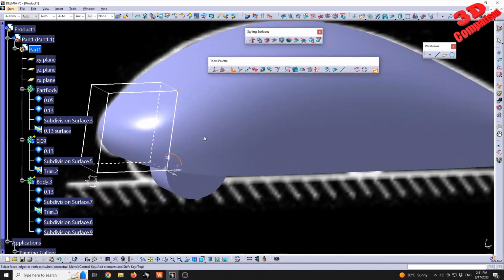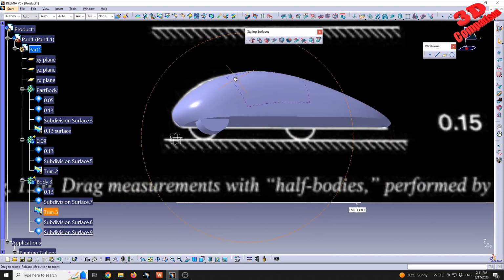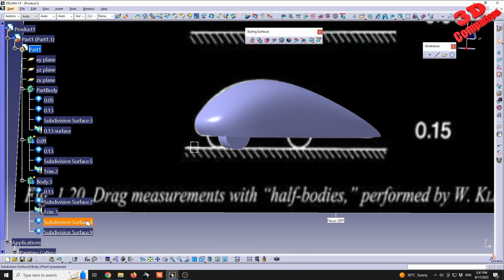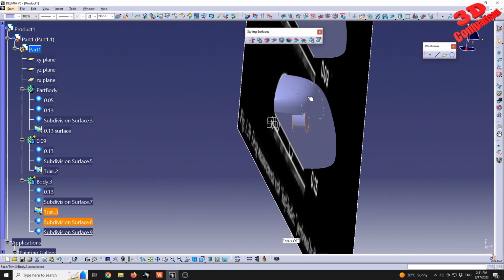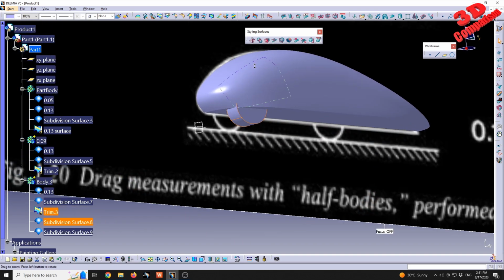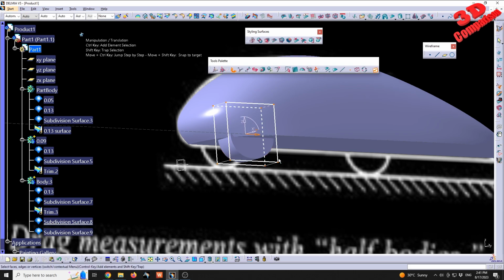We see a little bit of overlap over here between that shape and the wheel, but we can slightly adjust that by either moving the wheel a little bit on the inside or adjusting the width, because now the width is quite large on like that. So let's scale it a little bit and center it. We can also do this in, let's say, post-editing directly in Surface with mirroring in GSD, but I prefer to do it like this in Imagine and Shape if it's possible and it's not, let's say, complex.